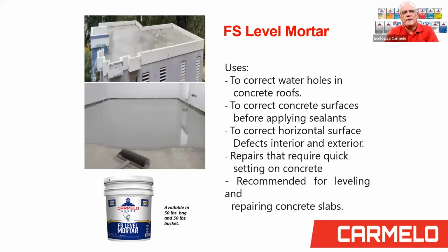Then we also have the FS level mortar. Here you can also do finished floors topping in interior, and also in the exterior. See on the bottom photo here, we did a room. We prepped it with a shot blaster or a diamond disc, and then we applied a primer to control the vapor drive, and then we installed the FS level mortar to get that finished floor level.